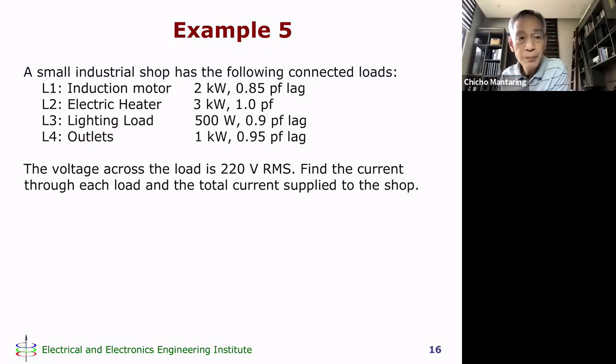Now your induction motor. If you look at the motor, it has what is called a nameplate, no? That nameplate will tell you what is the motor voltage, what is the motor current, but that nameplate will also tell you how many kilowatts the motor is, and more often than not, it will also tell you what is the power factor of that motor. So the induction motor in my shop consumes 2 kilowatts at 0.85 power factor lag.